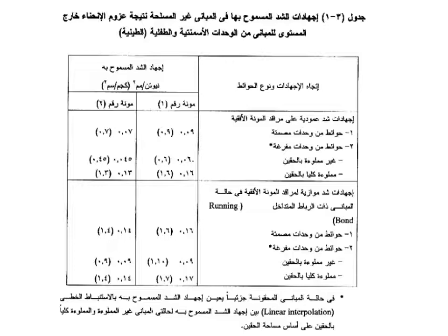However, if you are having an out of plane bending, the code allows you to take these values depending on the mortar grade, the type of bond, and the type of masonry units you are talking about.